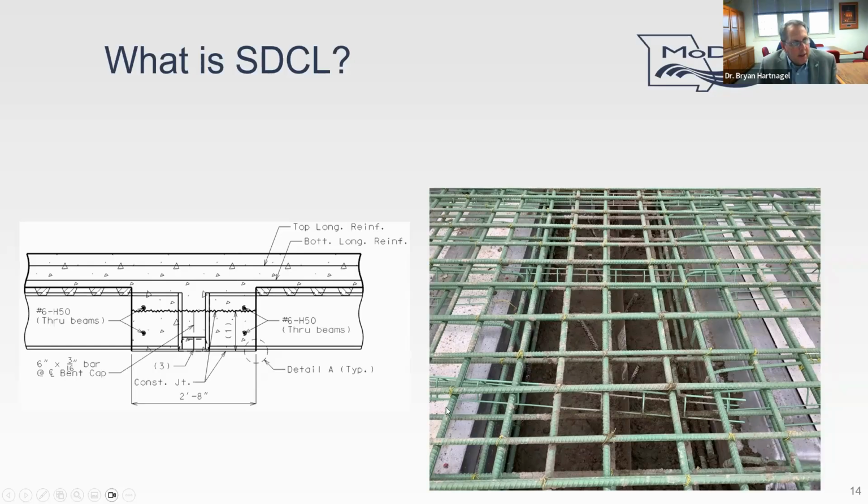In future ones, I think they didn't even put that in on the Northwest Bridge bundle and so on. But here you can see in the stay-in-place forms, this one is obviously square to the skew to the roadway. But in the stay-in-place forms, we use the styrofoam to fill the fillets of the corrugated or the corrugations so that we're not adding additional dead load. But there's the negative moment steel and so on.